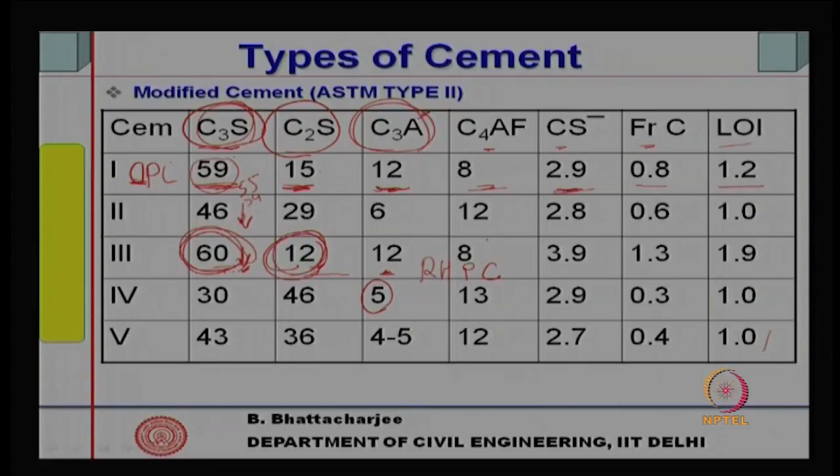Now, therefore, this cement is rapid hardening cement, because chemical composition wise this has got the highest C3S. Physically of course, fineness governs high fineness. Higher the fineness, rate of hydration will be high, and therefore, strength development will be faster. So, physically RHPC has two things, C3S is highest, C2S is least, because after all if you increase the C3S you have to reduce down something.